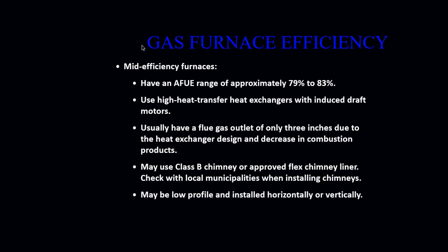However, it depends on the local municipalities and codes, where we have to look and see whether or not we can install these types of furnaces into an existing chimney. If the chimney is not capable of handling it, we cannot use it. We will have to use other means to ventilate these types of furnaces. They may be low profile and installed horizontally or vertically.